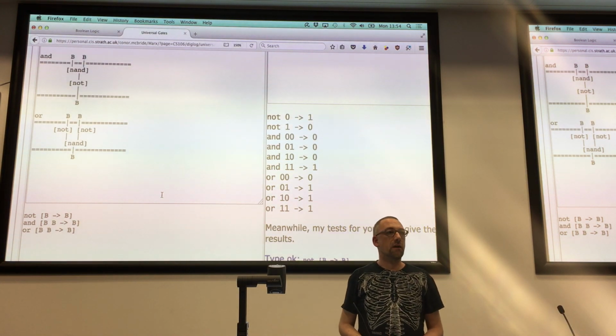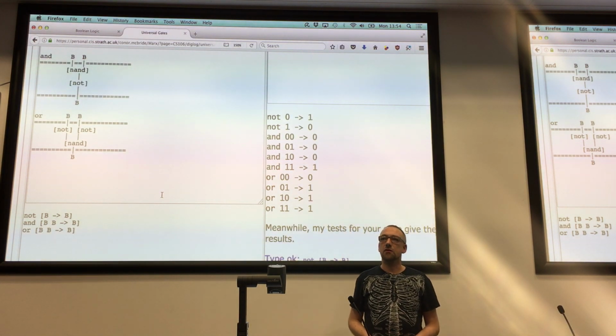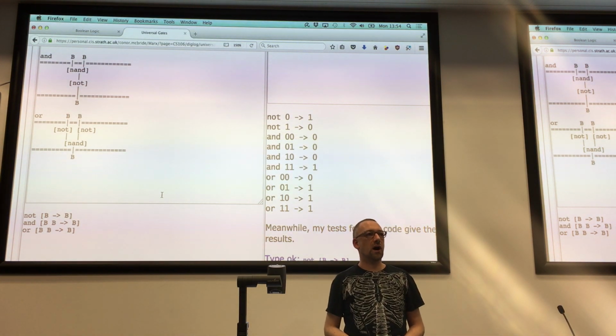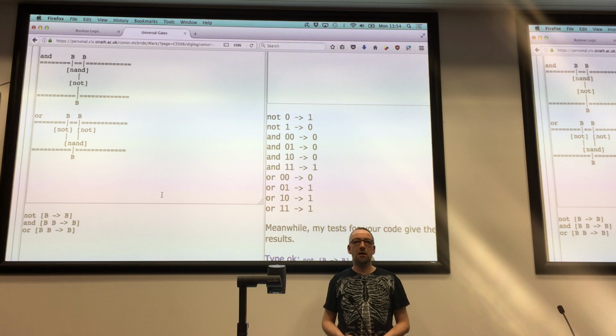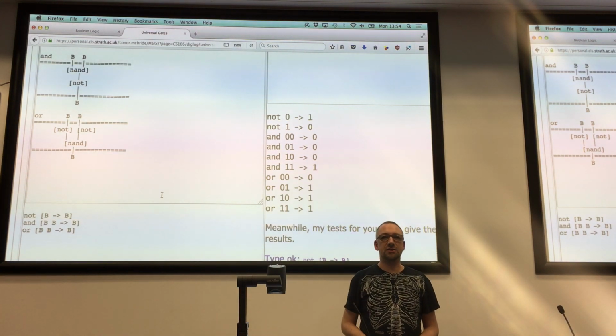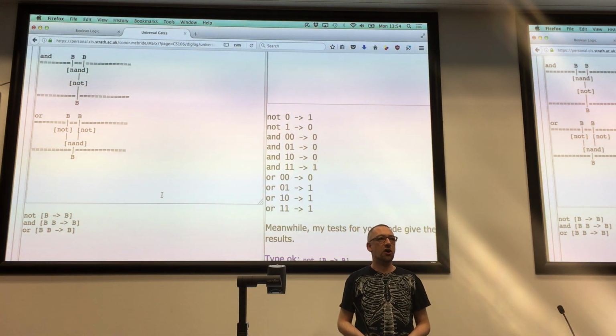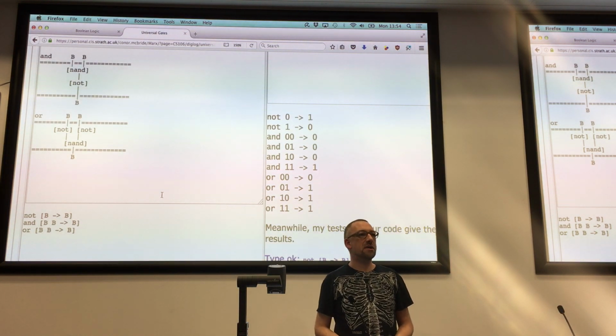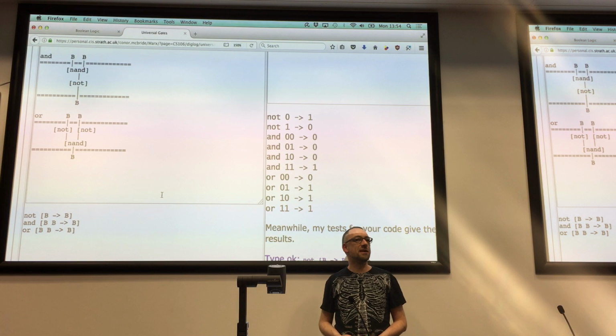And since you can represent all the logical formulae as disjunctive normal forms, that's to say built with OR, AND, and NOT, that means you can build any circuit you need from AND, OR, and NOT gates. And as you can build AND, OR, and NOT gates from NAND, that means you can build everything out of NAND gates.